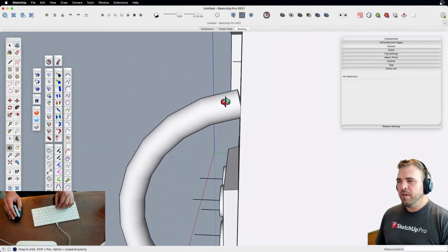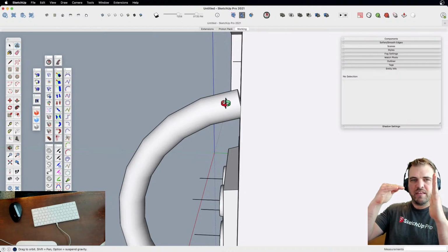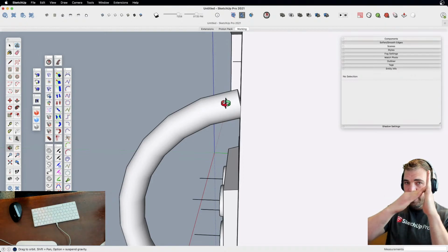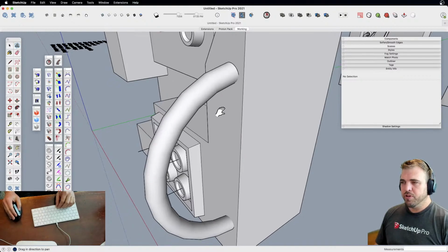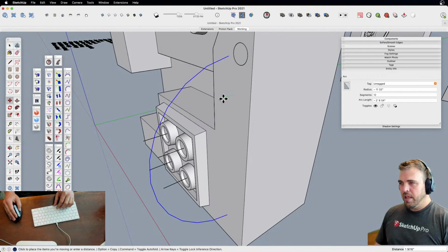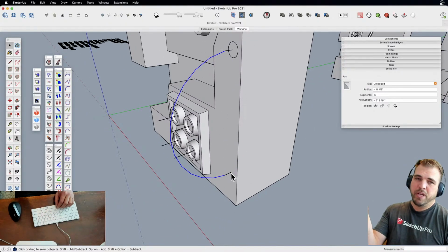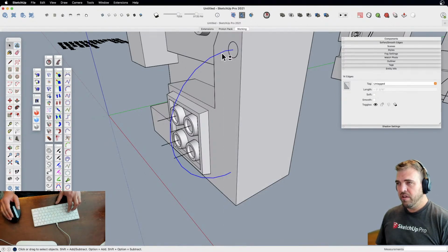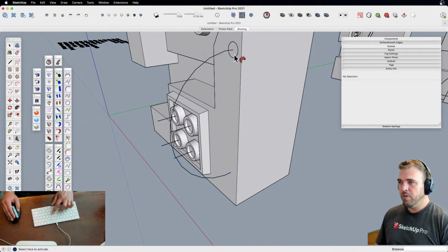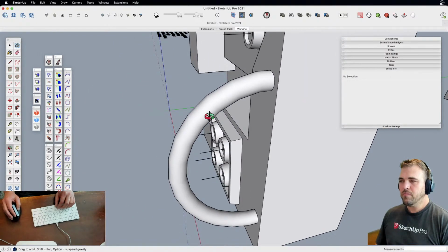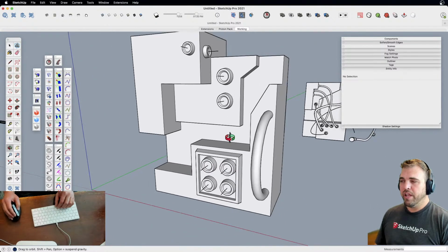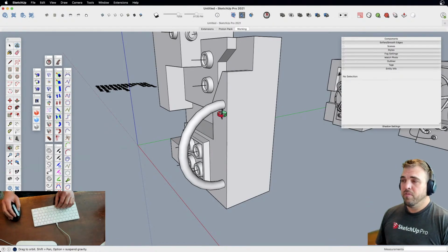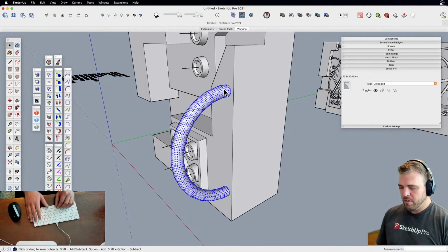What you'll see is this gap, because Follow Me is following the arc, and the arc doesn't hit the surface at a perpendicular angle. It hits it at some angle based on the type of arc you drew. So what you want to do is pull this away a little bit, and draw a straight edge that is perpendicular to finish this out. This is actually something we'll want to use even when we move to Bezier tools, because we're going to have the same issue. I'm going to select all of these and weld them. You could right click, but I've got that assigned to a shortcut, Shift W. So I've got that welded, Follow Me, and now it meets correctly. So from up here to here, I could do a simple tube like that. That's one way to do it, fairly straightforward. Okay.